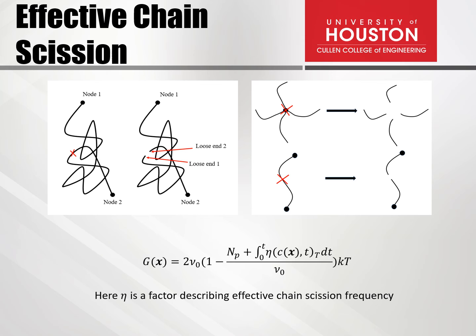In our case, any types of reactions related to chain scission will generate imperfection, which is similar to the loose end. Due to the undetermined reaction mechanisms, we are not going to treat them in detail in this study. Instead, we introduce a parameter called transition efficiency to include the chemical, thermal, and cross-link formation breakdown effects.